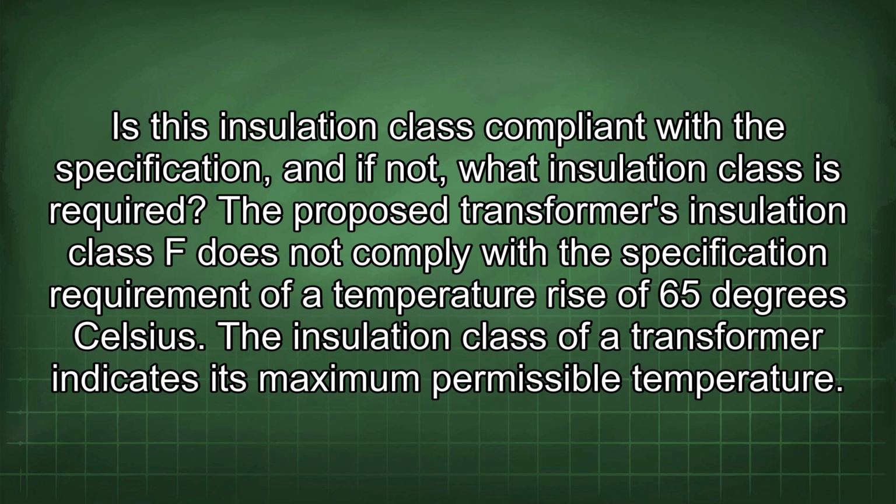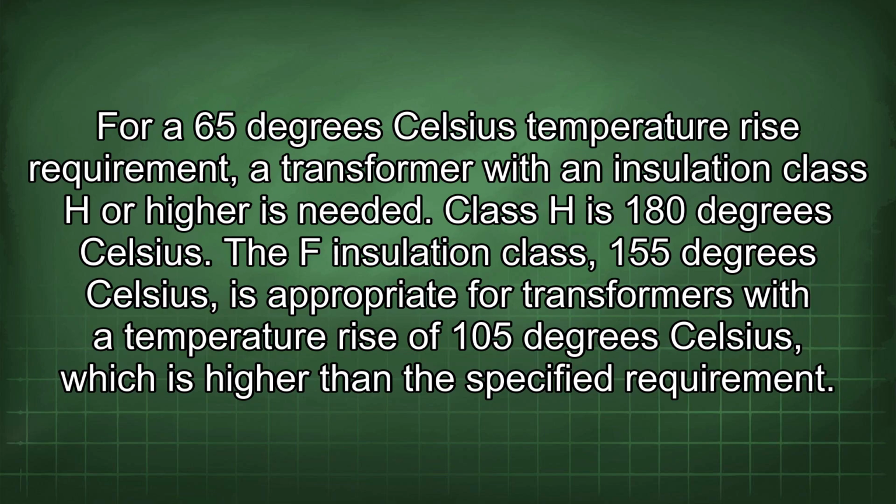The proposed transformer's insulation class F does not comply with the specification requirement of a temperature rise of 65 degrees Celsius. The insulation class of a transformer indicates its maximum permissible temperature. For a 65 degrees Celsius temperature rise requirement, a transformer with an insulation class H or higher is needed. Class H is 180 degrees Celsius.